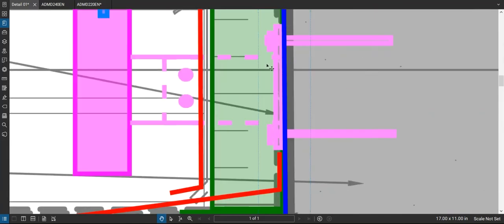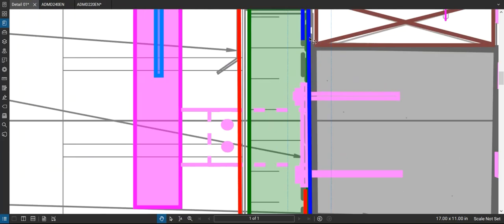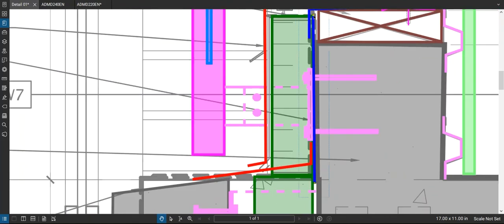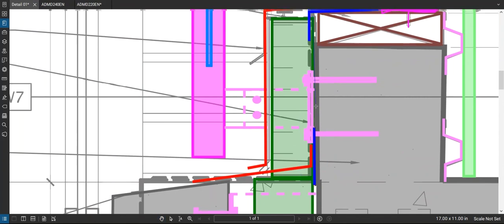The membrane could go in behind this bolted connection here. So this is kind of a self-healing type product. It's got some thickness to it, and it would be pretty reasonable there. You could also put some over top of the connection as well, but for simplicity here, I'll just draw it like this. I've put some behind the flashing, and then what I'm going to do here is, actually, what should happen here is, let's drag this one down. When you want to show all these overlaps happening in your details, it would be something like this.